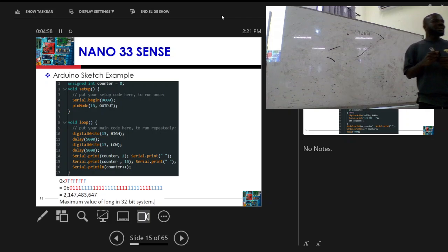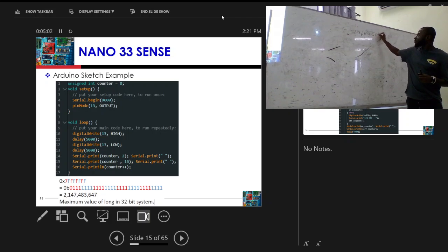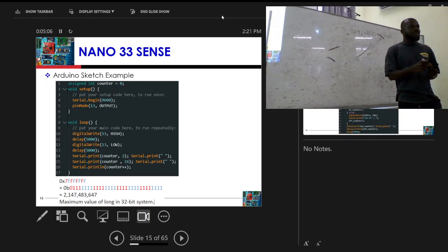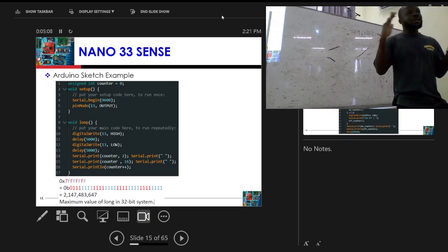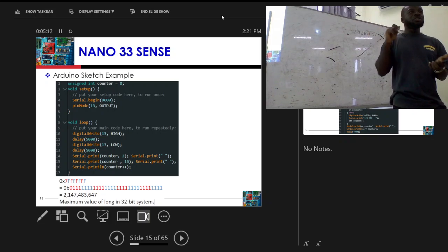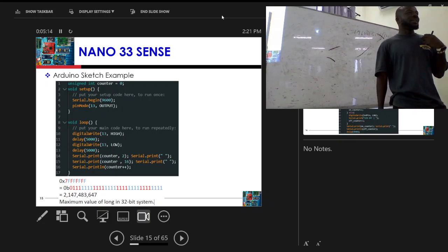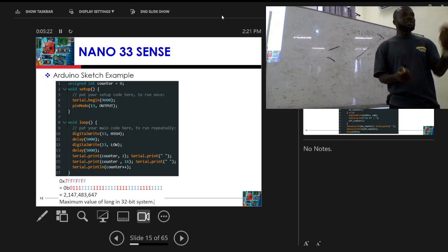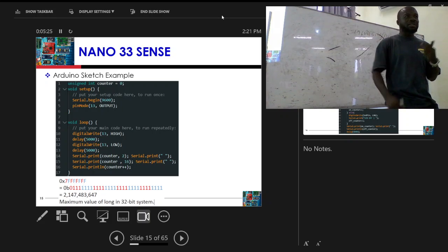So it means that we are transferring 9,600 bits per second. Within 1 second, we are able to transfer 9,600 bits, right? If you don't do this, there will be an issue between the PC and the Arduino board. At what rate should the PC send data, and at what rate should the board receive the data? There will be an issue if you don't do this, right?